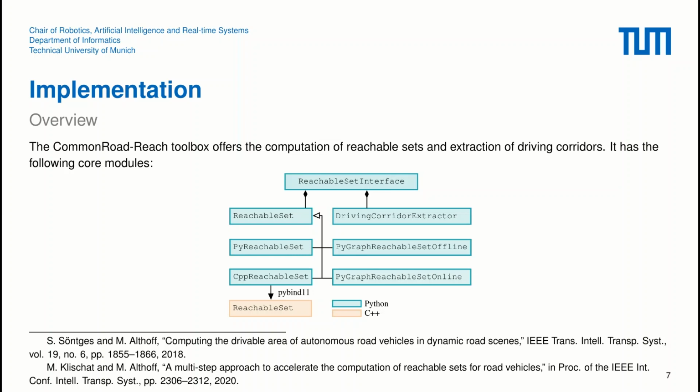In the polytopic set propagation method, we are able to include time-varying constraints on velocities and accelerations, which is not possible in the graph-based propagation method. In contrast, the second method avoids several geometric operations, rendering it faster in most cases than the first method. We refer the readers to our work for more computational details.